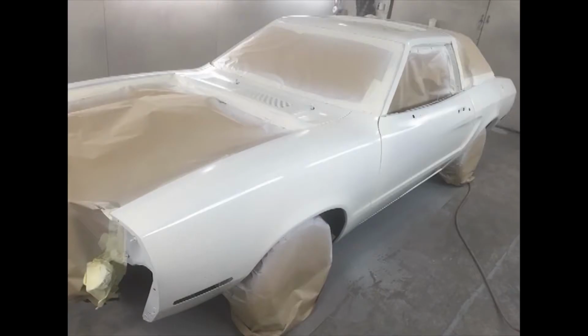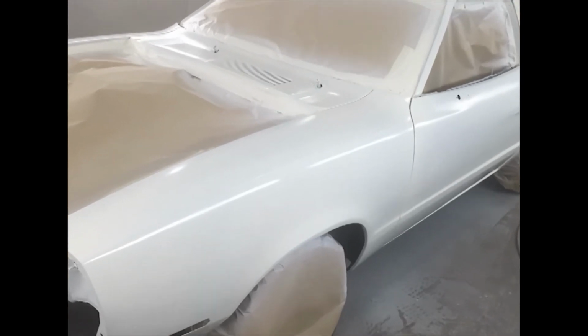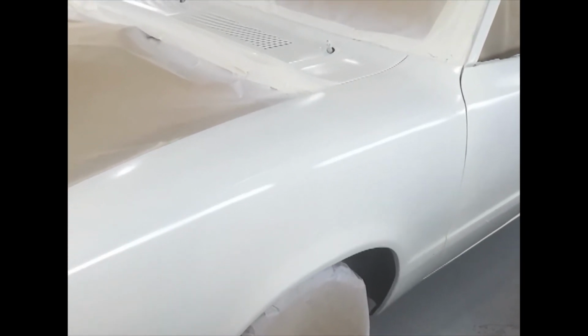Coming to the base coat, this layer imparts the actual color to the automobile. The integrity of this layer depends on its ability to resist weather, UV radiation and acid rain also. Most commonly, an acrylic based polymer composes the binder system of base coats. The addition of aluminium flakes to automotive paint imparts a metallic look to the paint's finish.